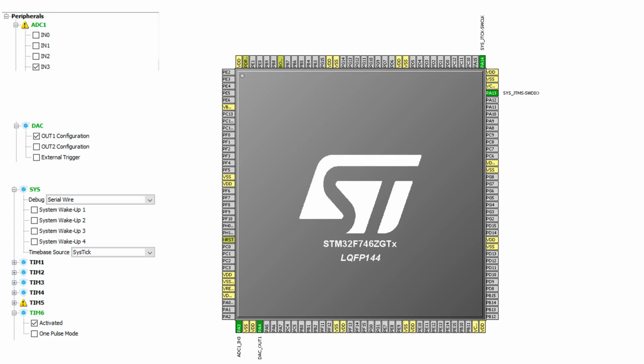And similarly, when I select DAC output 1 configuration, it is located on port A pin 4, PA4. Now on the Nucleo board, when you search for PA4, you see that it's actually mapped to an SPI line, but it doesn't matter. We're mapping that to the DAC, and that particular pin, PA4, according to the Nucleo manual, comes out on the CN7 connector, pin 17.